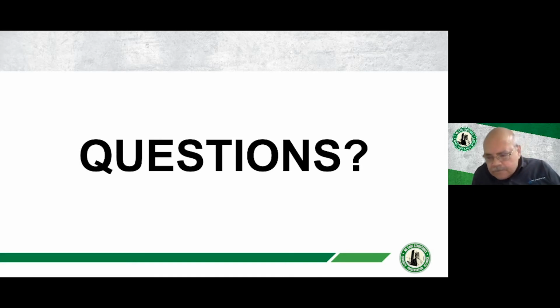Is there a non-destructive method available that can locate concrete footing covered with several feet of soil? Several feet of soil, I think we're in the mid-range or low-frequency GPR range. The answer is yes. Often we're asked to identify pile caps or footings if there's other installation or excavation. So 2 to 3 feet of granular soil, low frequency GPR.